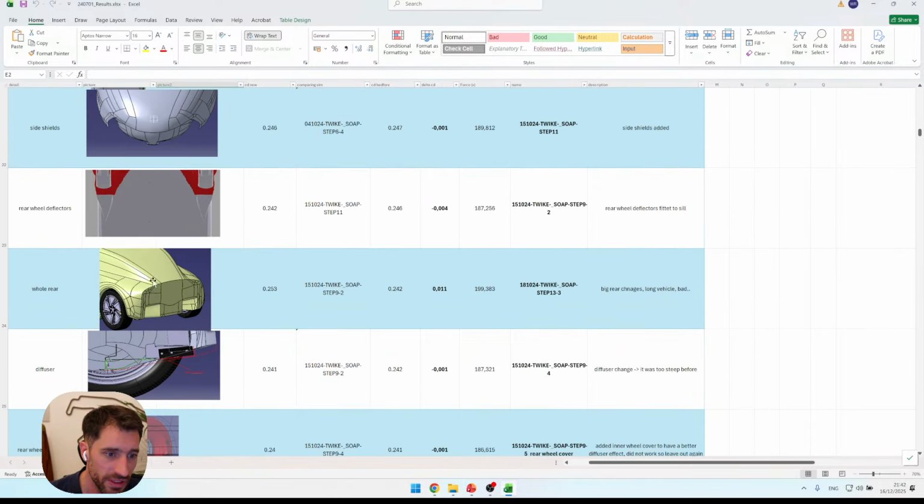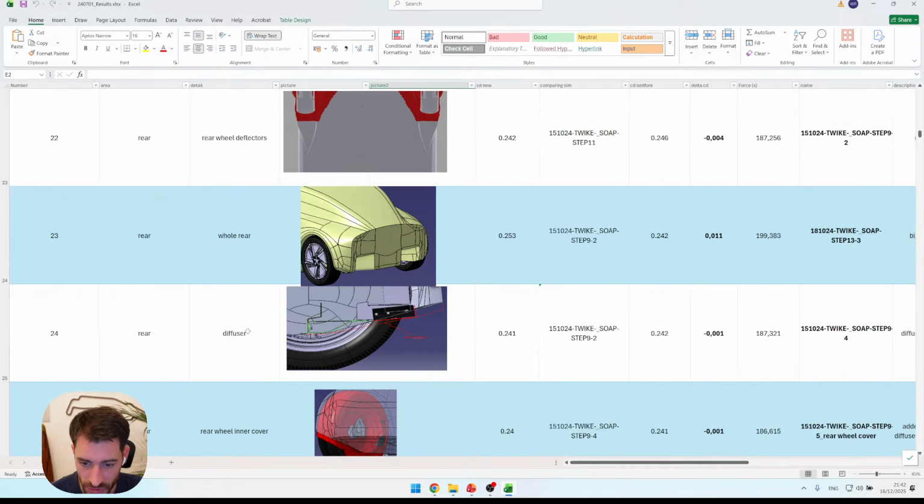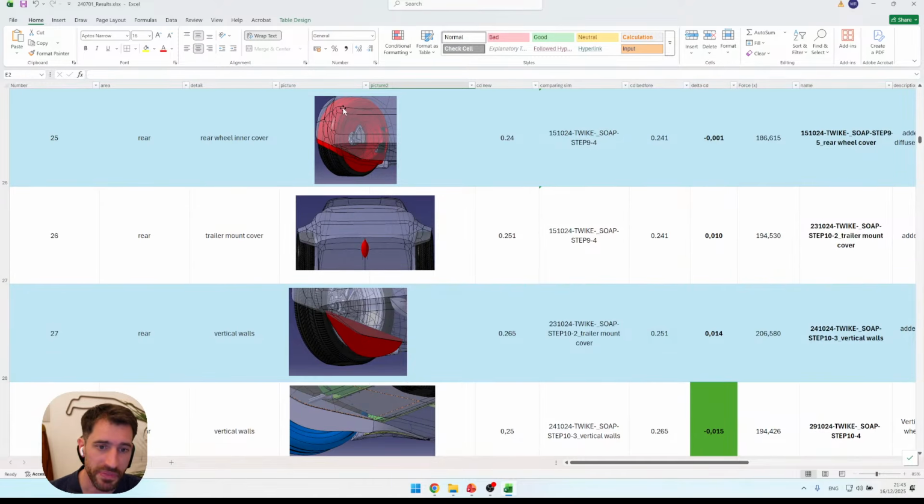We experimented with different channels for the diffuser. It was a very interesting exercise because there are hard points. Let me just zoom in. In terms of the chassis points, the hard points, we also had to work with a trailer connection point because this car can actually tow a trailer. The suspension was actually going through the diffuser channels at some point, so we worked with moving parts to shield that with slot gaps to move the suspension. We looked at adding covers to the wheels themselves, which would move together with the wheel to shield or control the tire wake.